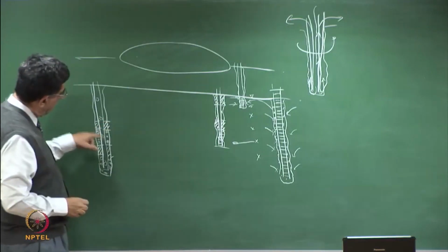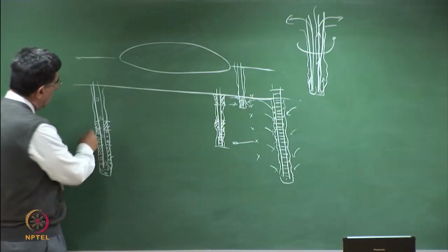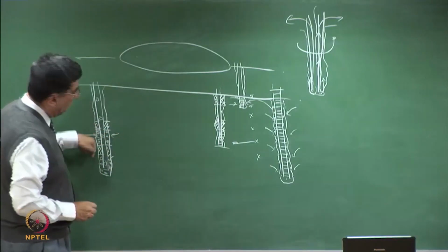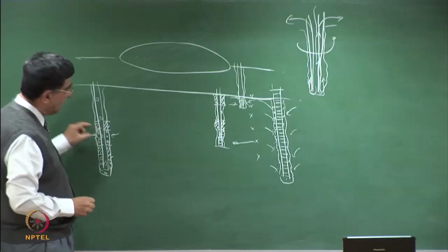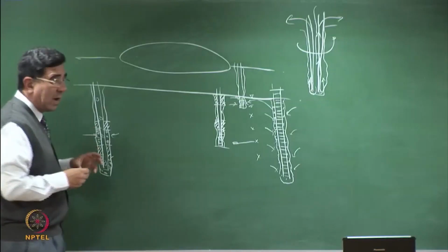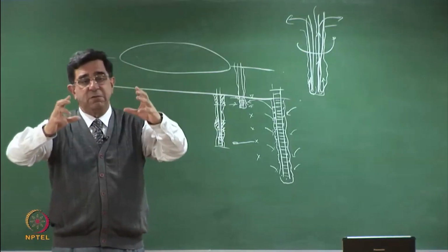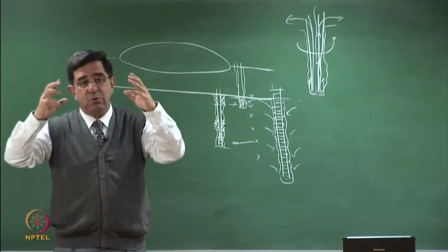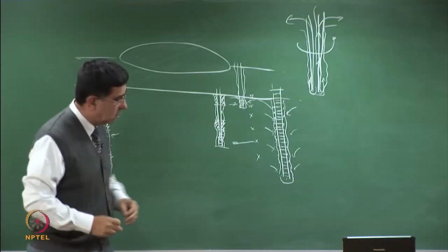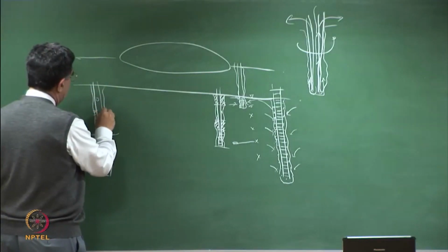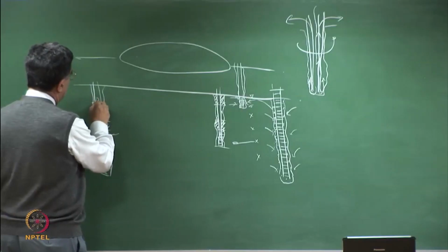So that when I come to this hole and take the water, water only comes from here. The top water cannot fall into this. This is the zone of your sampling. So a multi-port device has multiple levels of sealants in the annular space between the pipe and the borehole. That is critical. Then again you put gravel here, and then you put your bentonite seal.